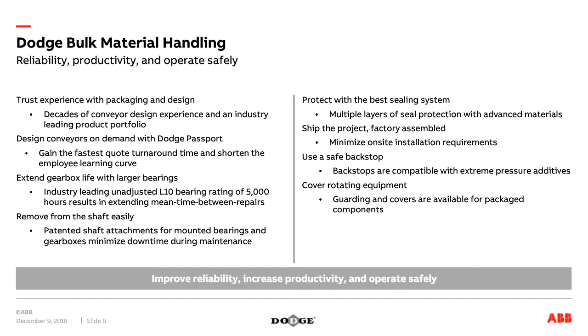Keep in mind, backstops are commonly used in bulk material handling applications. And when you have situations where lubrication with extreme pressure additives is used, not all backstops are compatible with the EP lubricants. That is one thing that's standardized with our heavy-duty gearboxes. The backstops we've designed are compatible.